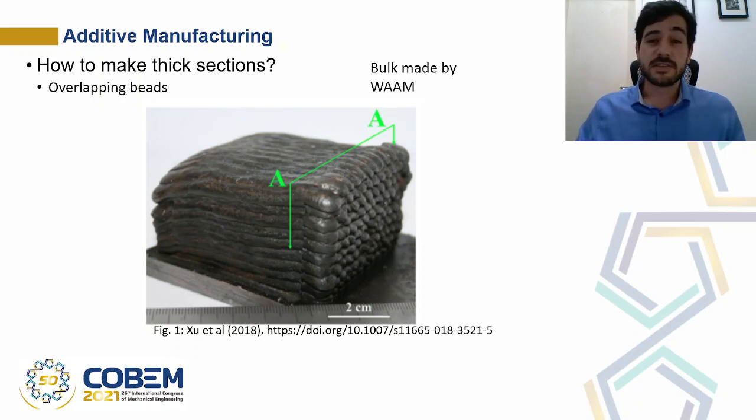An uneven surface may lead to the accumulation of errors in the vertical direction. After the deposition of several layers, this error is summed, and when it's not in consonance with the thermal gradient, the heat input, and many other parameters involved during the welding process, it can lead to huge effects in the geometry of the welding beads and the part being built itself.